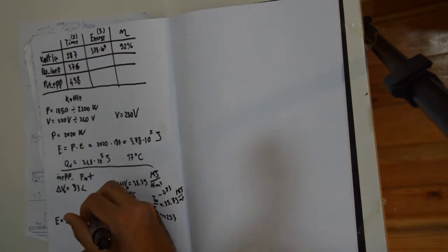But then actually the same water that condenses on the sides of the pot is then again evaporated, and probably that evaporation is mostly due to the same heat that is from the pot. So during the boiling process we will have some moments when we're using a superior heating value and some moments where we're using an inferior heating value. I'm using the inferior heating value here because in the end you end up with no water, with no condensation, so I assume that you're not actually using that energy. I mean, you use it in the beginning and then you lose it in the end, so it's good to use this one.